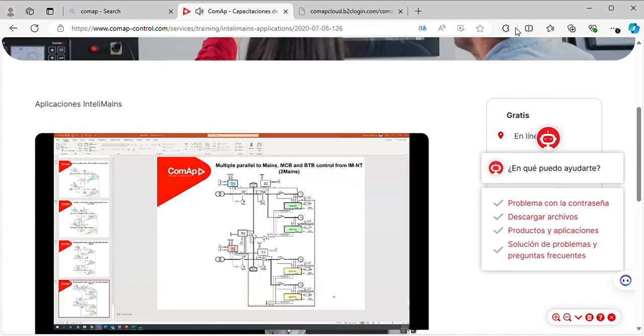Yeah, so it is trying to synchronize now. You can see the synchroscope is coming up, and once voltage and phases are matching, both of them are running in paralleling mode, but there is no active kilowatt, so they are not fighting each other. Once I see everything is operational, I go and close the MGCB, and now the gensets will start load sharing between them, so they can keep taking more load, and it will perform standard load sharing and var sharing.